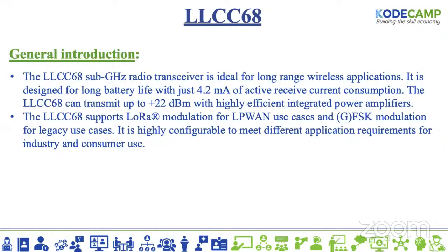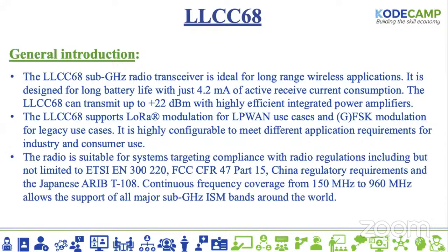It supports LoRaWAN and also supports frequency shift key (FSK) modulation, which is very good, and the radio is suitable for systems targeting compliance with radio regulations, including all these regulations I just mentioned. The continuous frequency range is from 150 megahertz to about 960 megahertz, so it depends.